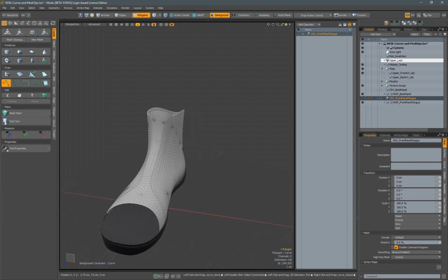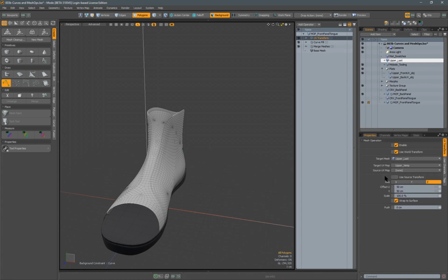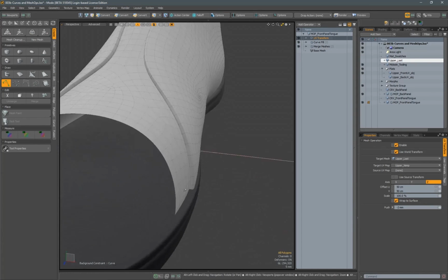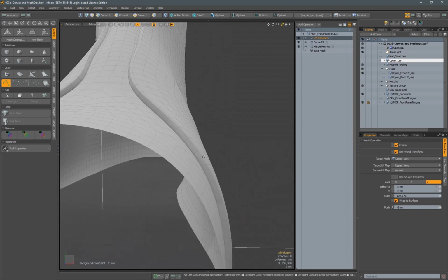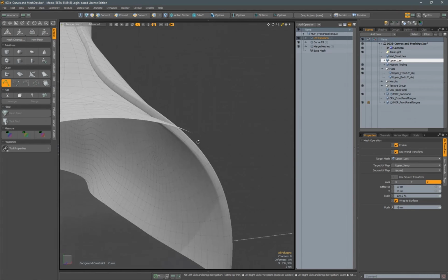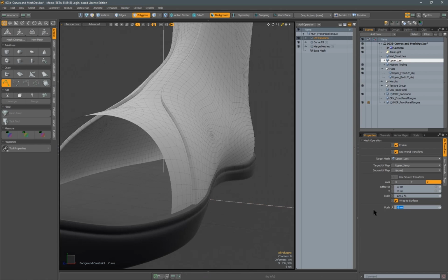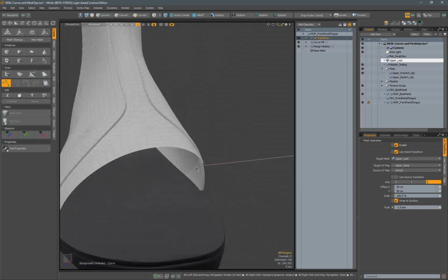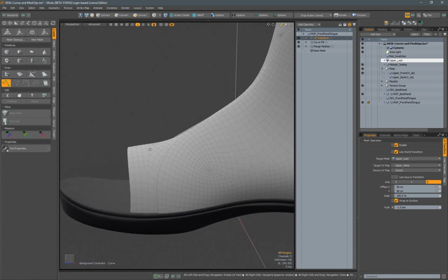of the last. So now let's go ahead and expand out the mesh ops for the mop version of this. And we'll go ahead and use the push tool, and we'll say negative, let's see, we'll try negative 0.2, and that should be pretty harsh, but that should work just fine. That accommodates the exact thickness that we created for the previous panel, but we don't want it to be dead precise like that. So let's go negative 0.15 centimeters, and that looks a lot better.